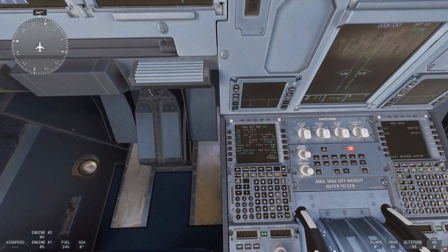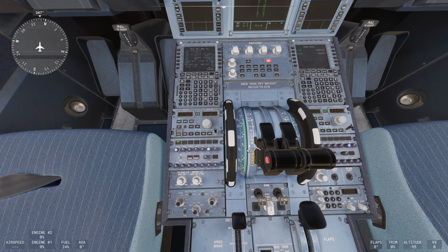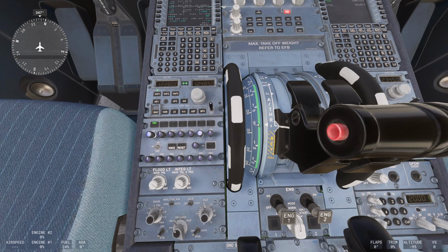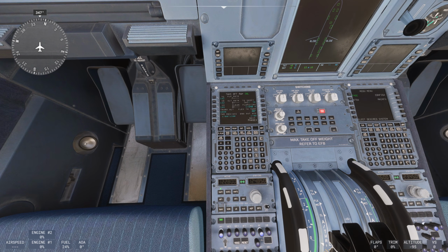So we've got a temperature in here of 68 degrees, and this means the aircraft will assume a higher outside air temperature and reduce engine thrust accordingly. If we need full power, we can always push those thrust levers to TOGA, which is takeoff and go around mode. And to set the flex takeoff mode, you have to go down to your thrust throttle quadrant and just make sure that we're on the flex MCT detent when we're pushing those levers forward for takeoff.